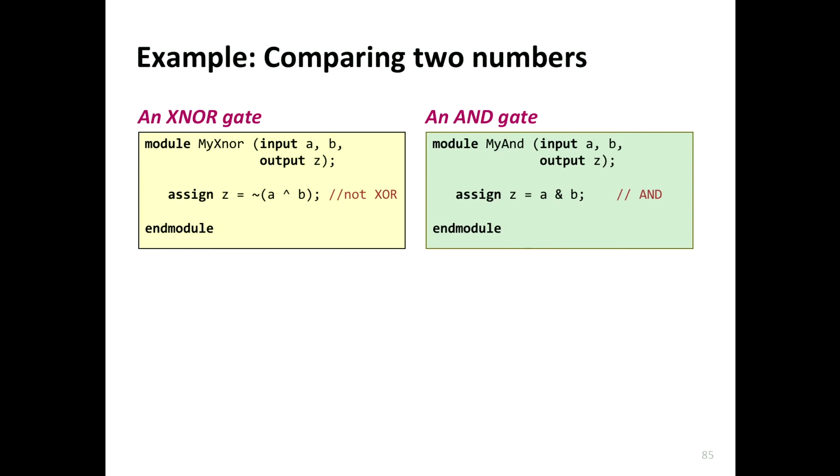Exactly. It actually does bitwise addition. So 0 plus 0 is 0, 0 plus 1 is 1, 1 plus 0 is 1, 1 plus 1 is 10, of which the lowest part is 0. So typically, when you're doing A plus B, you will pretty much be implementing an XOR. Got it?